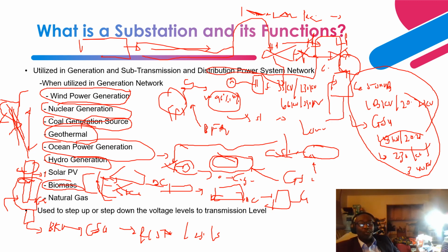Then it goes through a feed water system, a feed water pump, right? There's a drain water pump that feeds and pumps the water to the boiler to repeat the cycle. So that's how you obtain the complete cycle of our power generation, right? From here, it goes to a boiler feed pump, from the feed water heater pump, then from here it goes to the boiler. So that's how the cycle repeats.